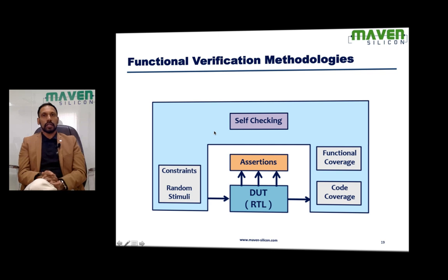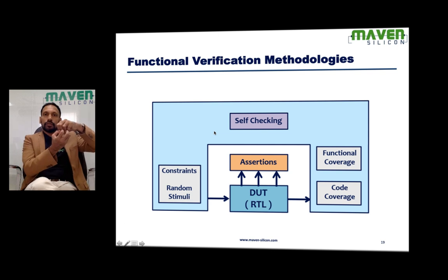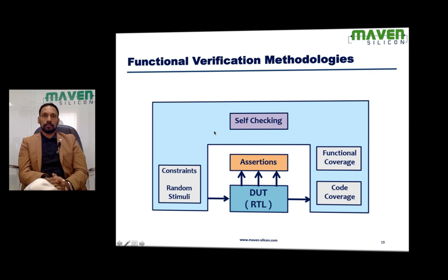That's where we try to apply verification methodologies, different kinds of methodologies. Even before running simulation, we try to verify the RTL code through linting. I'm going to explain these methodologies a little later. And before writing Testbench, we try to define all kinds of test scenarios as part of the verification plan. We want to be more methodical because that increases our confidence level. We don't want to write Testbench straight away, like, okay, this is the specification, this is the design, and I'm going to write Testbench. It doesn't happen like this.